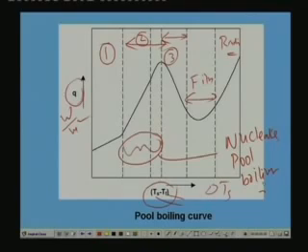In this region you can see that the heat flux increases quite steeply with the degree of superheat, delta Ts. That means you get very high heat transfer coefficients in the nucleate pool boiling region. You also have what is known as the critical heat flux, at which the heat flux becomes maximum at a particular superheat.